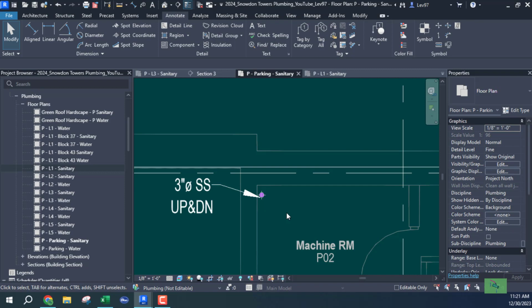Just be careful when you're doing that, because a lot of times your plumbing fixtures, if you're counting plumbing fixtures, they don't. And plumbing fixtures is a whole other argument whether to use them or not. I don't like to use them because they don't propagate through the pipes and through the fittings automatically like they should. So I kind of stay away from it.